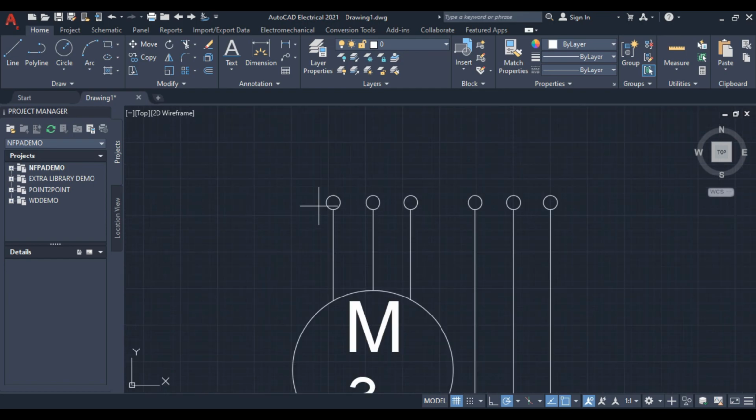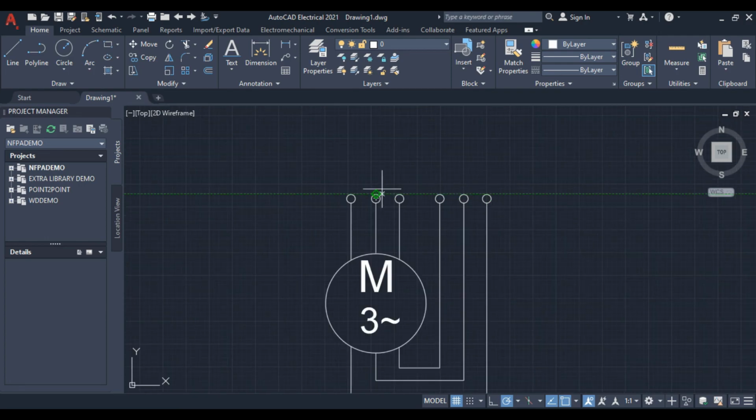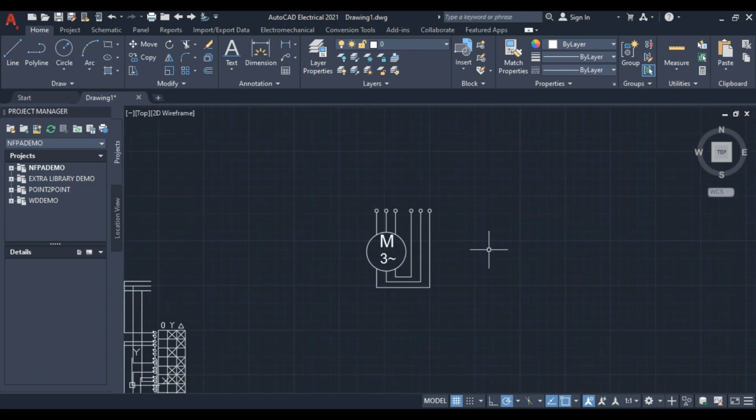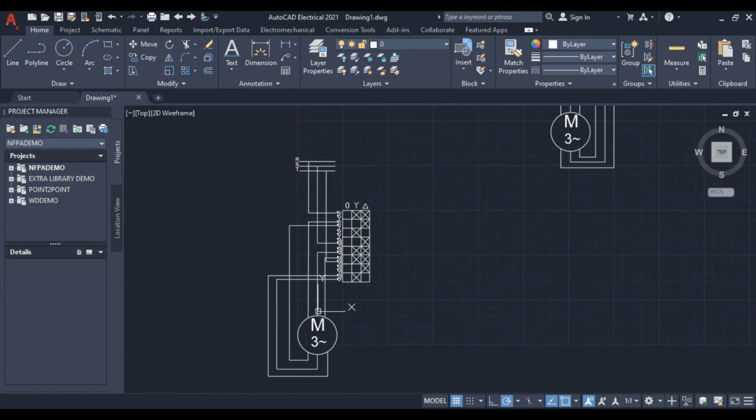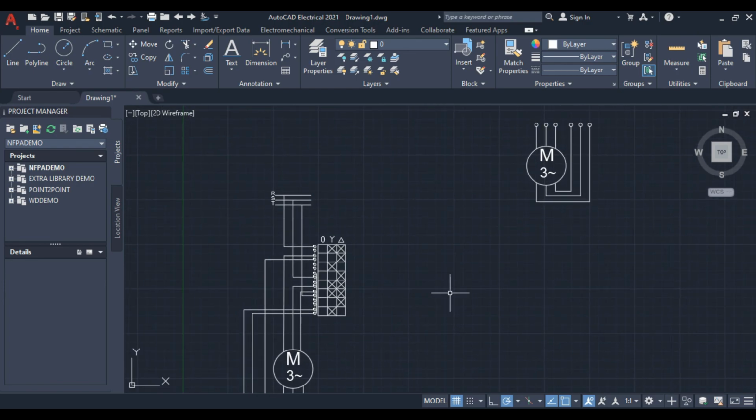And you will write in here, for example, U1, V1, W1, because they are the entry of your electromotor. And here you will write W2 and U2, V2. So the homework for you is to connect this electromotor to this circuit, or if you can, this circuit plus the last circuit that I have drawn, the right or left rotating one. If you have learned that, connect the two connections, the rotating one that is coming in this, that will change the rotation, and it will change the delta or star connection.